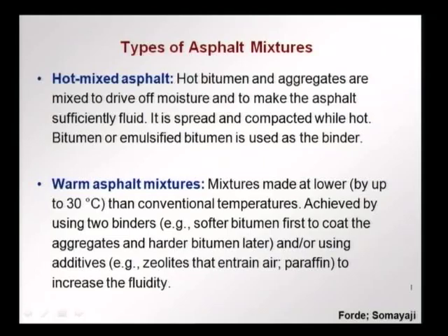So, the bitumen is heated say to temperatures of 150 to 180 degrees centigrade, and aggregates are also heated up, the whole thing is mixed together, and in the hot state the material is spread out and compacted as it is cooling.